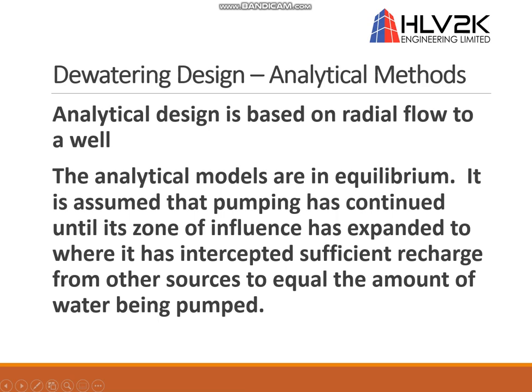I would like to emphasize that the method I'm going to speak about is based on the analytical method. The analytical design is based on the radial flow to a well. The typical analytical models are in equilibrium. It is assumed that pumping has continued until its zone of influence has expanded to where it has intercepted sufficient recharge from other sources to equal the amount of water being pumped.